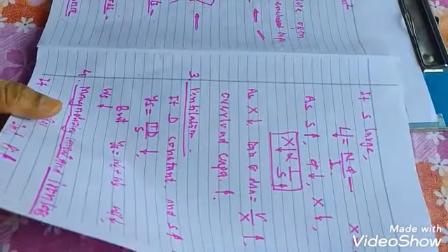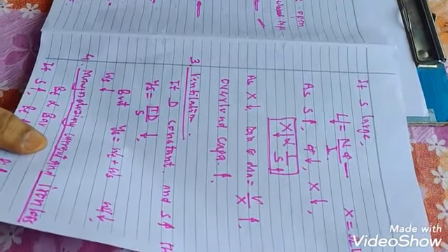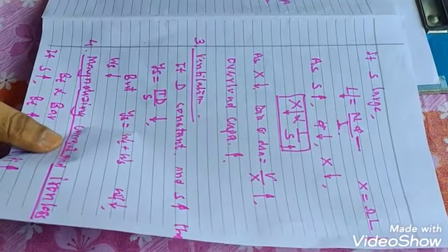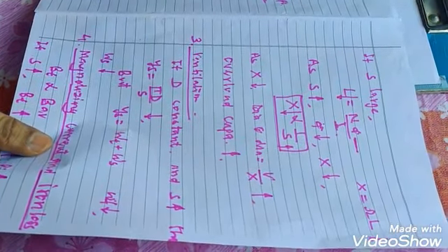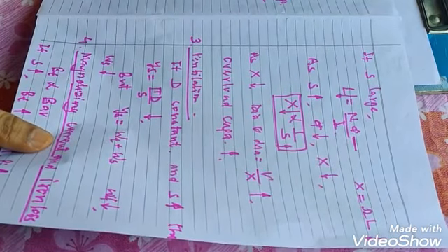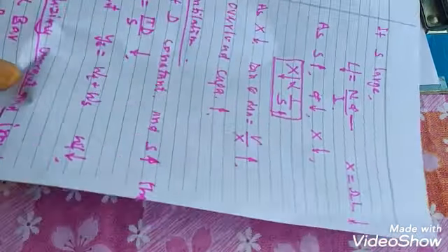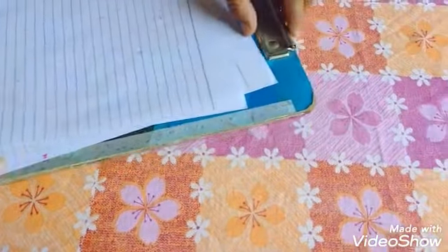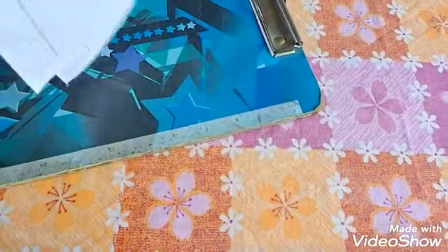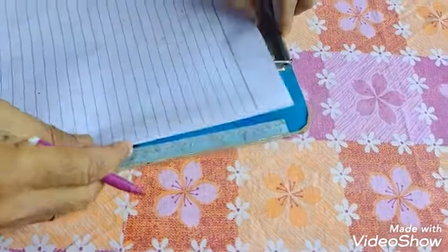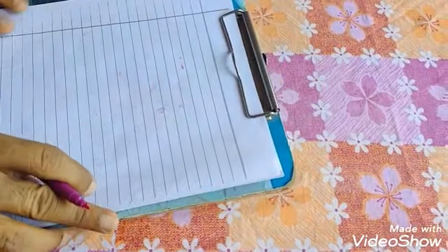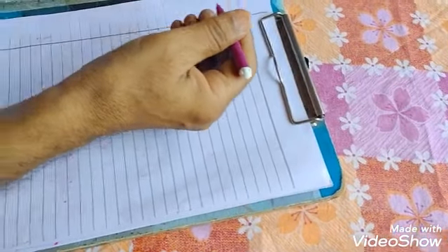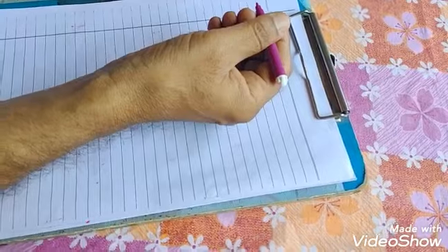So the flux density in the teeth should not exceed the limit, otherwise the magnetizing current is increasing. At the same time, iron loss in the teeth is also increasing, so the no load current is increasing, and due to iron loss the teeth get heated.